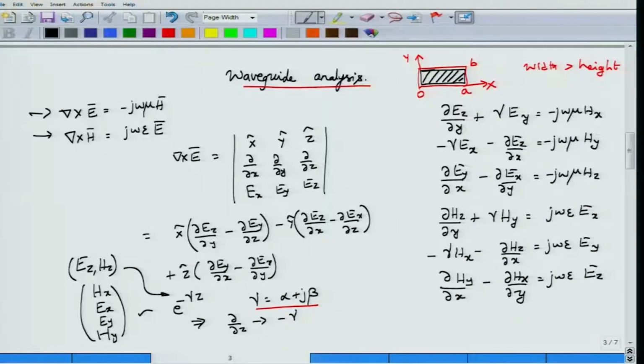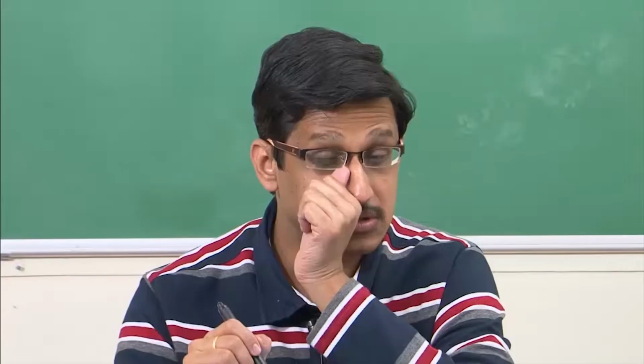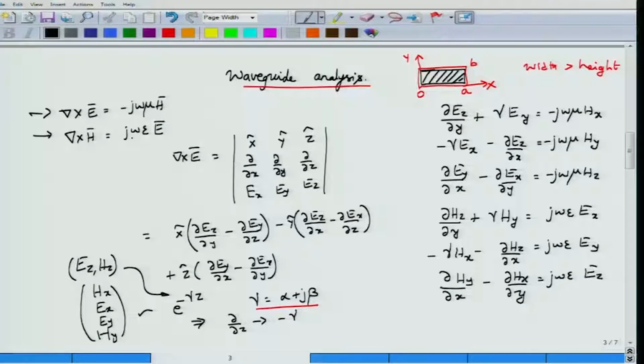So whatever current there is would be displacement current. I am also using, without telling you, that these are phasor quantities. So I am not explicitly indicating the time dependence, we are only interested in the spatial dependence, because the time dependence is taken to be in phasor form. So del by del t becomes j omega, the integral becomes 1 by j omega, and because of that we have written this as j omega. We will also assume that mu and epsilon are constants, unless we specify them to be non-constants.